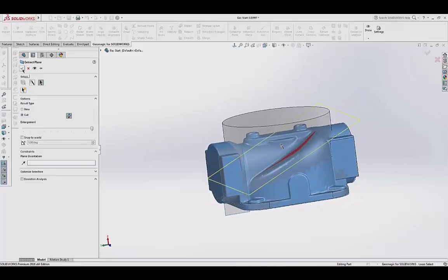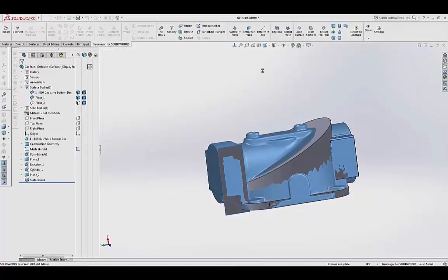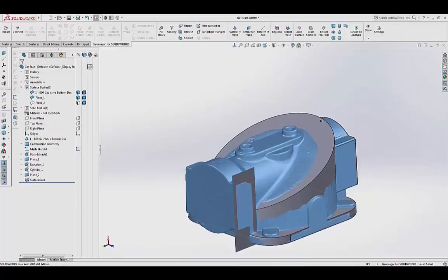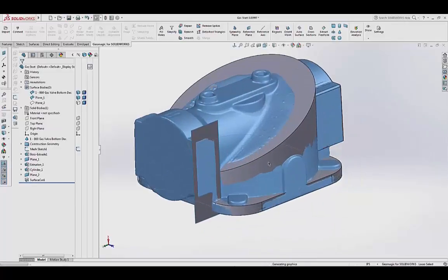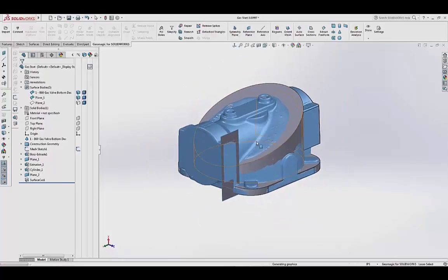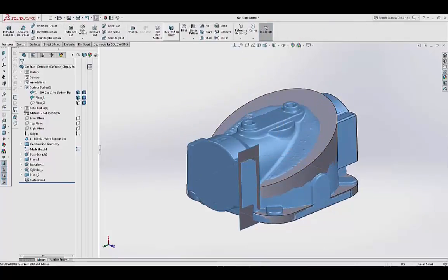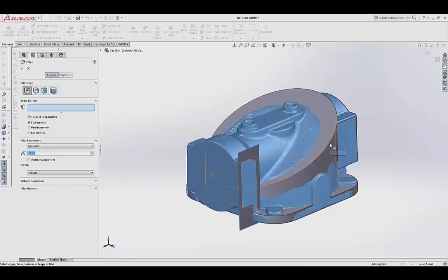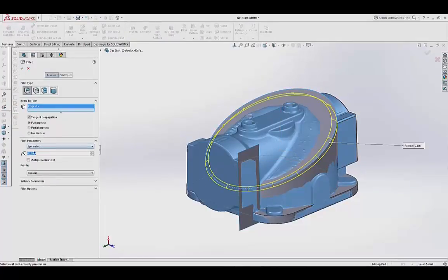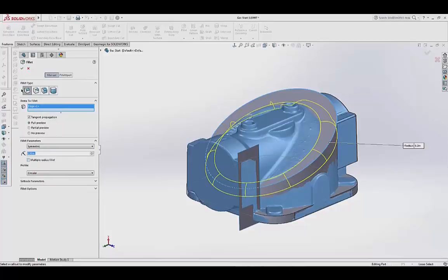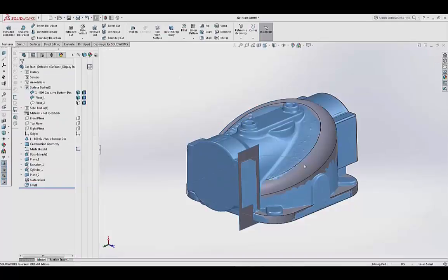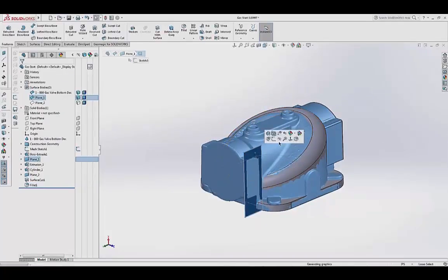You see here I can change the enlargement, and then it'll automatically create that plane and cut it away from the solid. And from here, intermixed with the tools that I'm using inside of SolidWorks, I can jump over to the SolidWorks tools and say that I want to throw a fillet on that edge. And then it makes it very easy to visualize. If I just type in 0.3 there, it looks like it's about a 0.3 fillet.